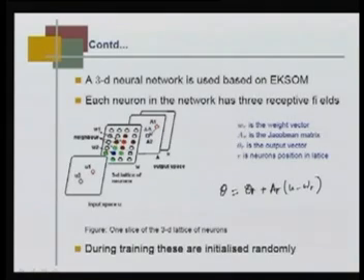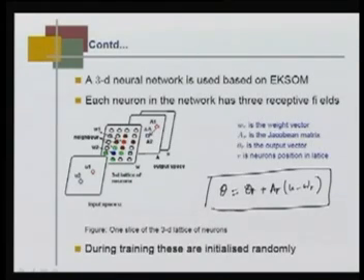And then we map the input space to output space through a Jacobian matrix A by this relationship using Taylor series first order expansion, that is theta equal to theta r plus A r times (u minus W r). So, W r is the associated reference vector, A r is the Jacobian.